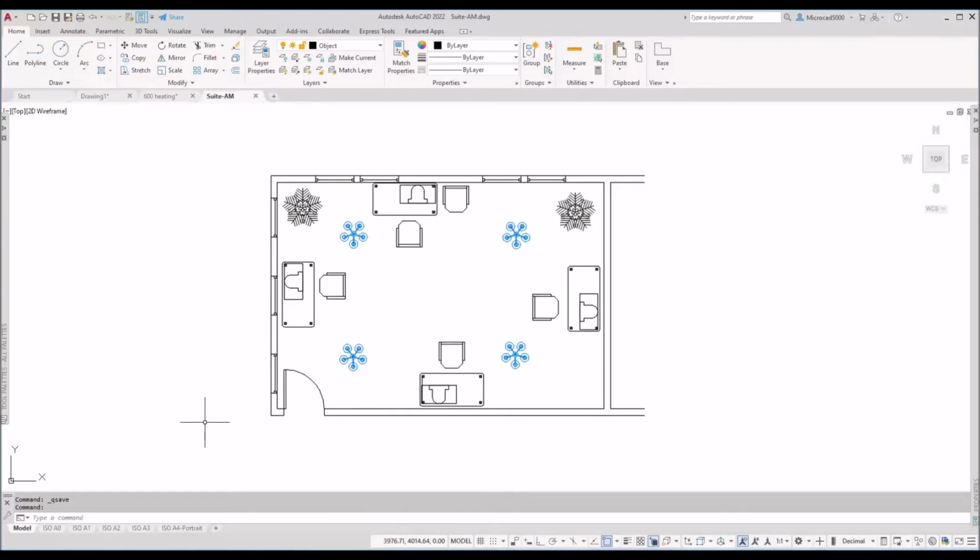So yes, now selecting objects, you see that prompt all the time. There's all of my modify commands on the ribbon there, home tab, modify panel. And it doesn't matter which one I go into, copy, move, rotate, mirror, whatever. I've got the copy command. There's that prompt on the command line, look, select objects. You see that prompt time and time again. You use it every day. When you go into AutoCAD, you will see that prompt on this command line every day. Now, I'm sure you're all aware that to select an object, you put your cursor over it, wait till it pre-highlights, and click on it. And it shows you these dashed lines as you select them. So picking them one by one, nothing new there.